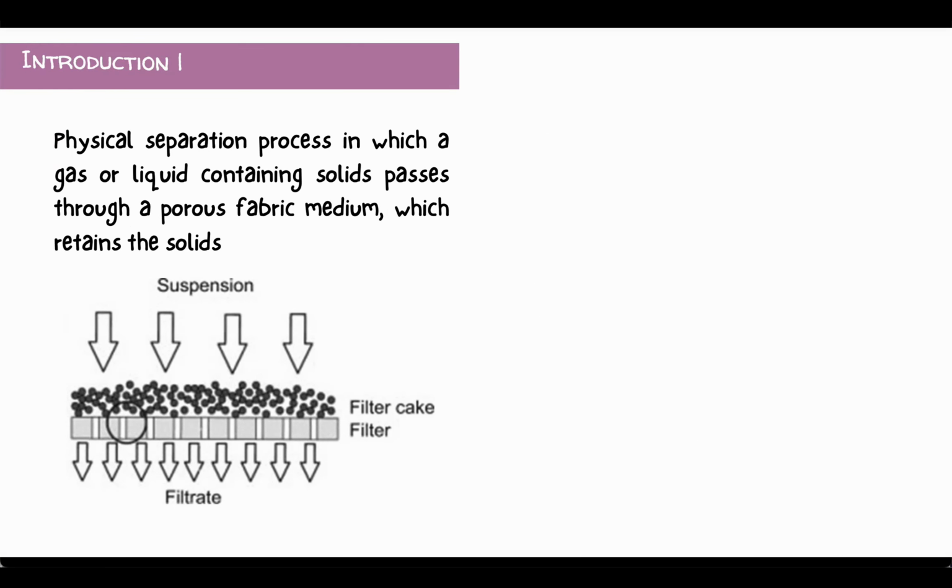Filtration is the separation process of removing solid particles, microorganisms, or droplets from a liquid or a gas by depositing them on a filter medium, also called a septum, which is essentially permeable to only the fluid phase of the mixture being separated.